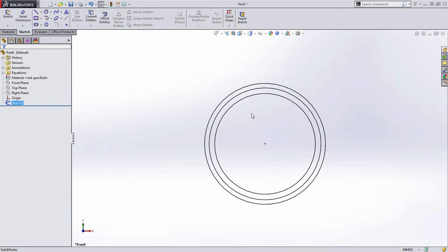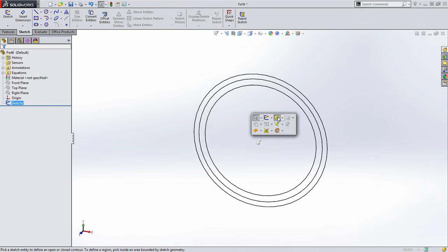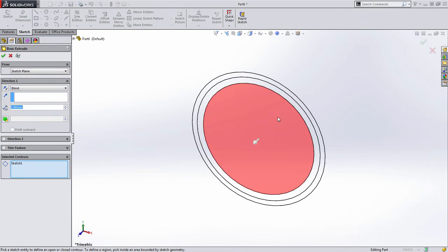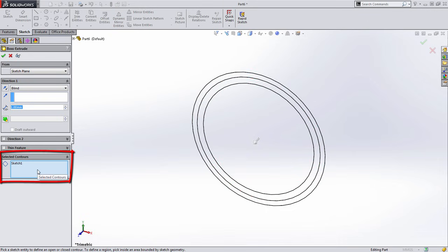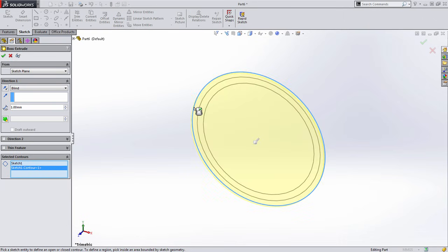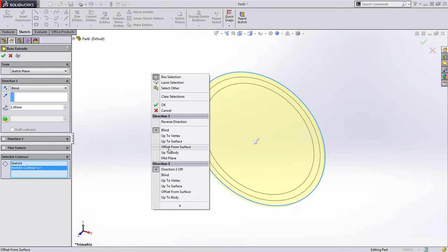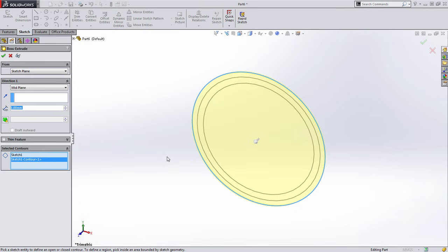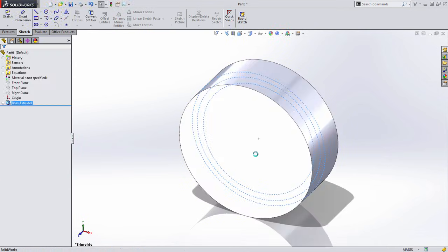At this point, I just want to go ahead and extrude this. With a sketch selected, I'm going to choose the extrude command, and you'll notice that because this sketch contains multiple profiles, SOLIDWORKS has enabled selected contours. Selected contours allow you to select just portions of your sketch. Now, we could select each one of these regions, but you can also select the outside diameter to capture that whole circle. I'm then going to right mouse click and choose a midplane extrusion type, and I'm simply going to drag out this value to 20 millimeters and right click to finish it.